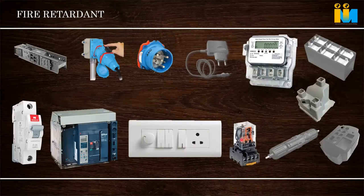So this is a special application for relay, because normal transparent polycarbonate has a V0 at 3 mm of thickness. But when we are designing this part for 1 mm thickness, as per the regulation, as per the safety, we should take a raw material which is certified, or has the property, 1 mm V0, instead of 3 mm.